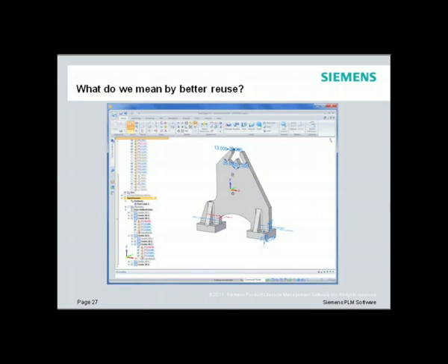You're going to see us take a SolidWorks model and bring that into Solid Edge. We can open SolidWorks models directly. And then what we're going to do is take the drawing of that same part, and use the drawing to inject the dimensions off of the drawing onto the part itself, and then use those dimensions to edit the part. So, again, you're going to see the solid model and the drawing sort of merged, where the manufacturing dimensions off the drawing are pushed into the solid model, and then the solid model is edited with them. And with that, I'll let the video speak for itself.